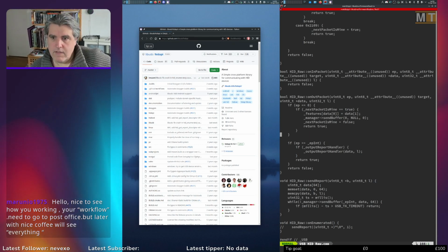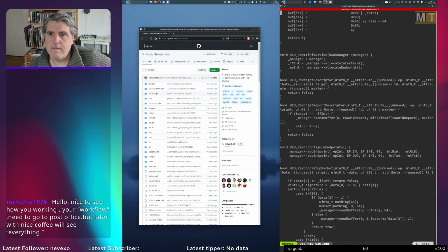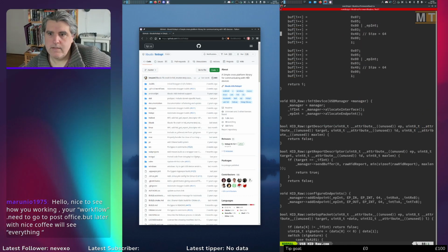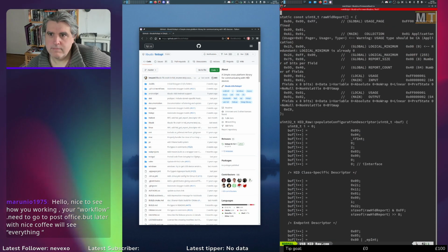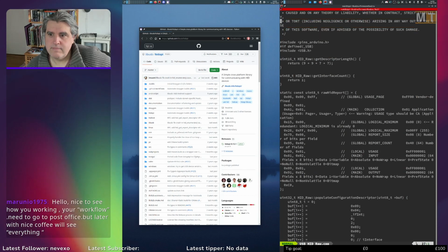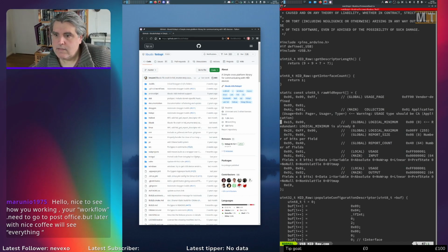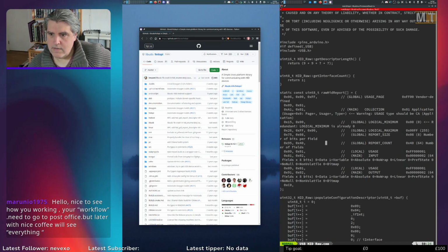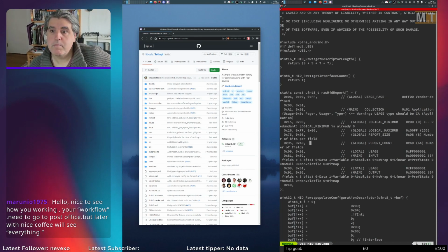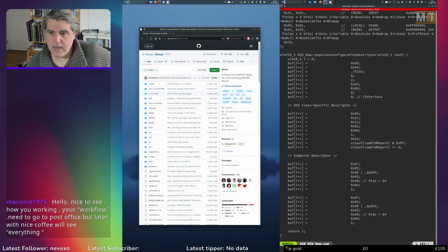And we have feature requests, which acts a bit like memory. A HID report is 64 bytes maximum. So we can send reports or receive reports of up to 64 bytes.